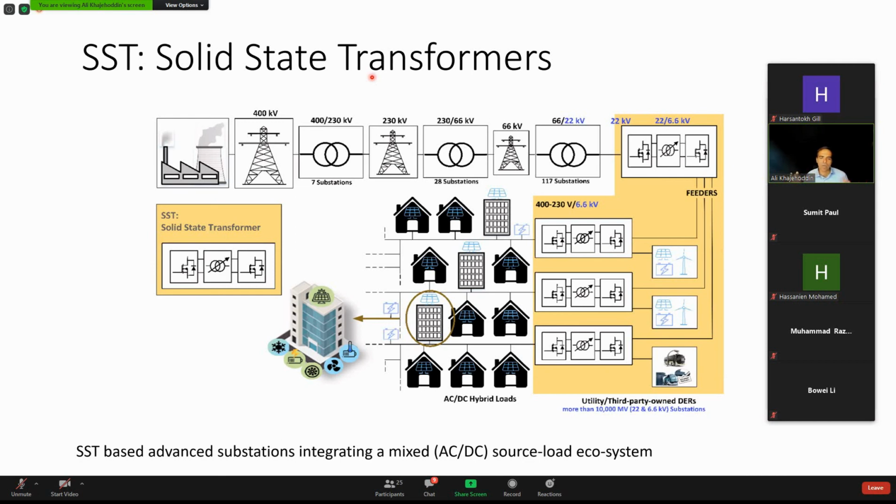A transformer, you apply voltage there, you get an output voltage and it will transfer the power. There's no control there. But with a solid state transformer, you can just replace a normal transformer. They can reach even lower volume and better efficiencies. And you can place it in different locations to connect different things to each other. For such systems, you don't have to have everything in AC. And the problem with AC is that it has so many losses involved.